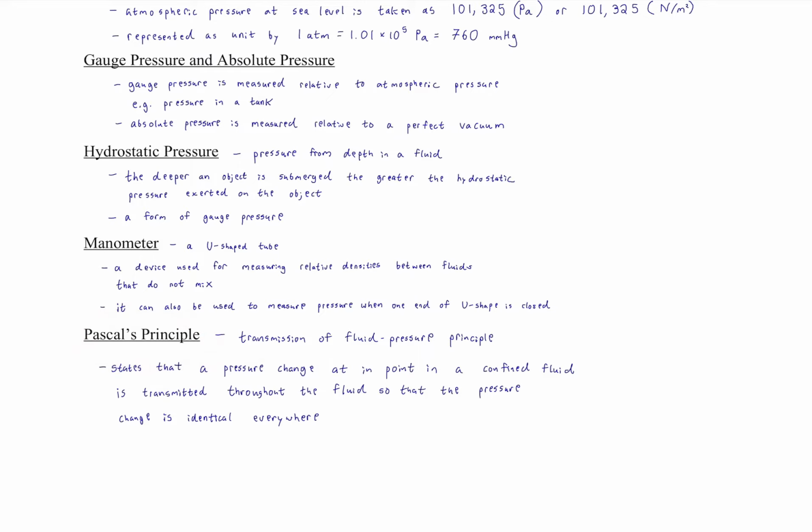That's important because Pascal's principle allows us to understand the ideas of hydraulics, which is a fluid-driven lever. In other words, you put a little bit of force in and you get a big force out, which is fine as long as you give something up. Energy is still conserved, and you have to give something up, just like with a lever. You have to give up the convenience of being able to push close to something. You have to have a really long lever arm, or the fluid equivalent of a really long lever arm, when we're applying Pascal's principle.